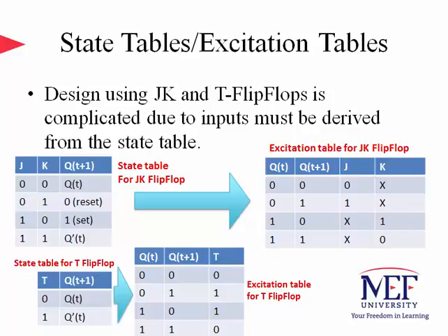To derive the input equations, we need the functional relationship between the state table and the input equations. This functional relationship is usually illustrated with something called the excitation table of the flip-flop. The excitation table for D flip-flops is simple because the next state depends only on the input, nothing else. This operation with D flip-flops makes the sequential logic circuit design simpler compared to the designs with JK and T